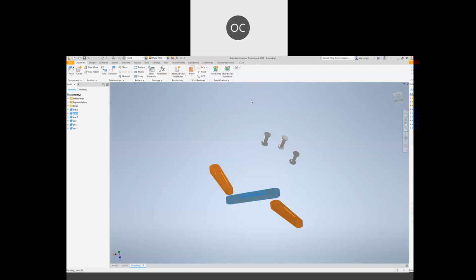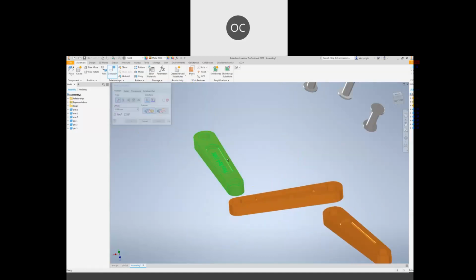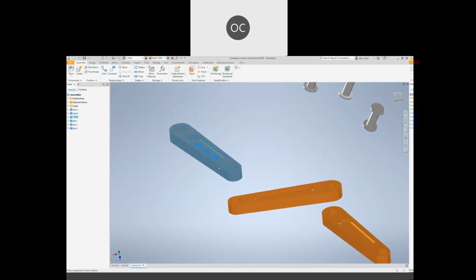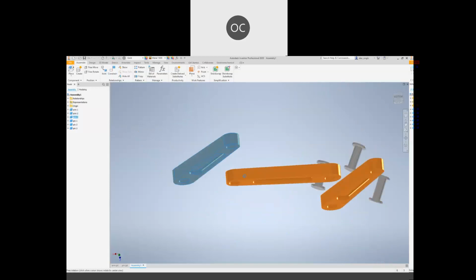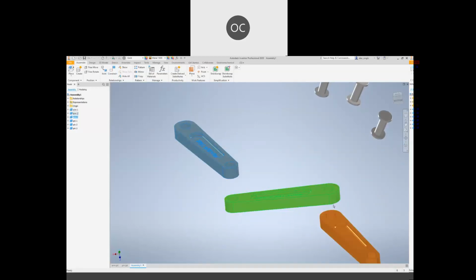That I would like to share with you will be also constraint. So now we are going to do mate also, but on surface. So you will see that supposedly, when you press escape and drag, you don't want this one floating. So supposedly this surface will touch the bottom surface, and then this one on the bottom also. So constraint, but this time will be mate, surface.